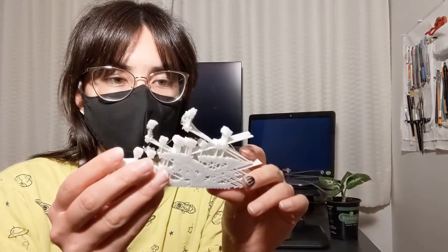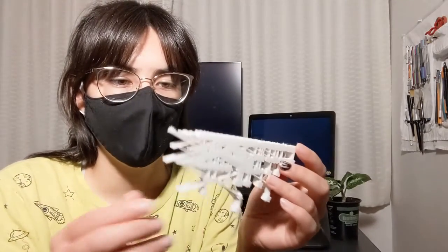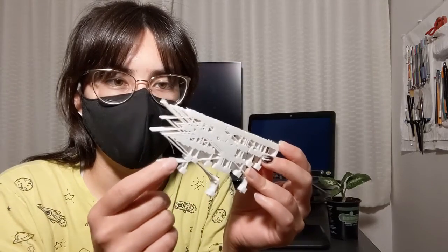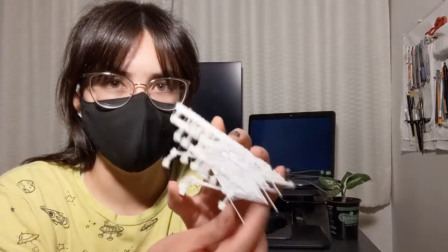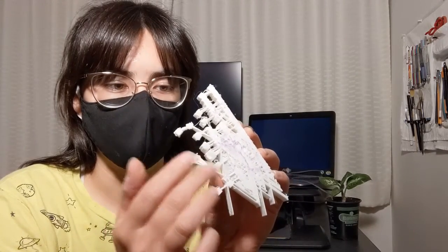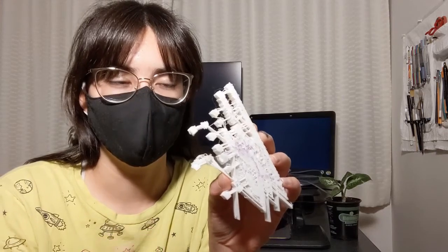I ran into a lot of issues printing this 3rd piece though. This is another one of the edge pieces. I believe it's sort of a bottom part of the tree. Since it's much sparser than the other 2 parts, there were a lot of build plate adhesion issues on the initial layers. And since these edges are so thin, it was really hard to correct for them.